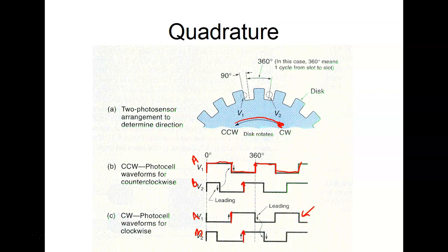So this is basically what we use on any device that has to give us a direction. This is what the robots have on right here. They have these quadrature encoders. If it goes one direction, it might count up. If it turns and goes back the other direction, it would count down.